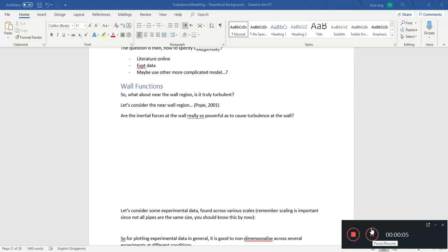And in the last few videos, I've talked a little bit about turbulence modeling, basically the K-epsilon model, and how the most basic of Reynolds-averaged Navier-Stokes came about, and the LES model, the most basic of which being the Smagorinsky model, and I've briefly covered some of the concepts in both of those models. Today, I want to cover something a little bit different.